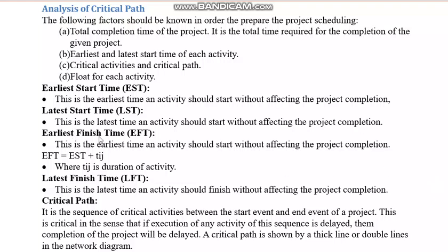Okay. Now earliest finish time. Earliest finish time means, if you have started with the earliest start time, then you will have earliest finish time. Suppose 5 o'clock you started, then 7 o'clock will be the earliest finish time. So now how will you arrive at earliest finish time? Now the earliest finish time is the earliest start time plus the duration of the activity. Duration of the activity we will say Tij.